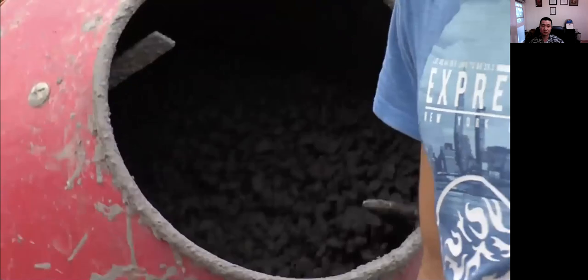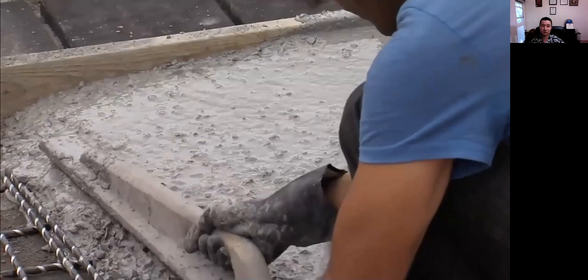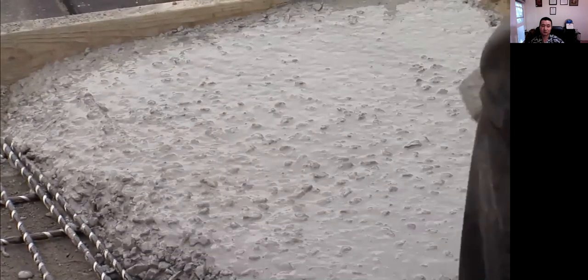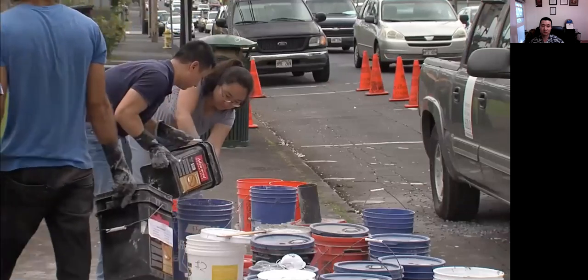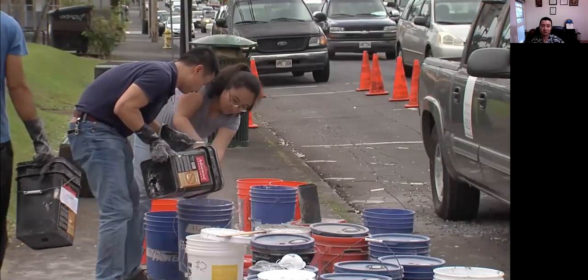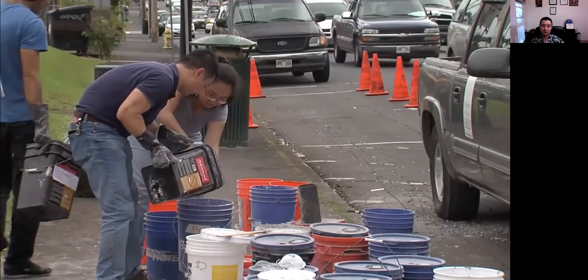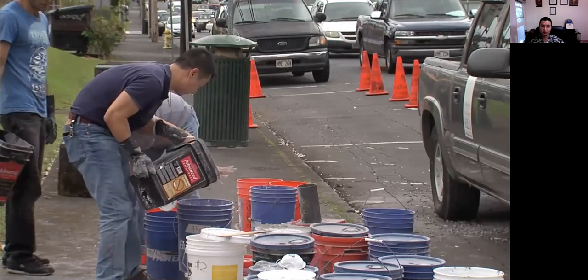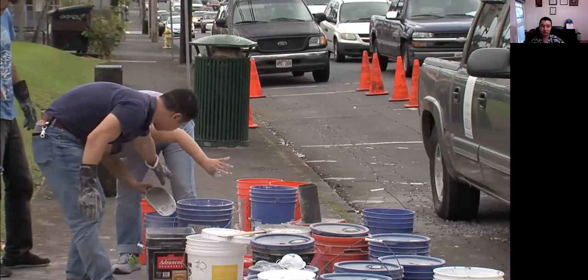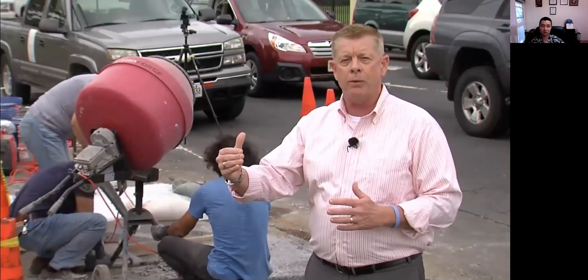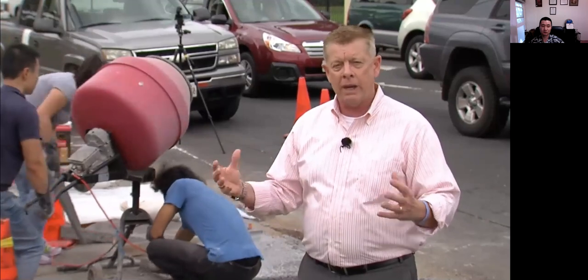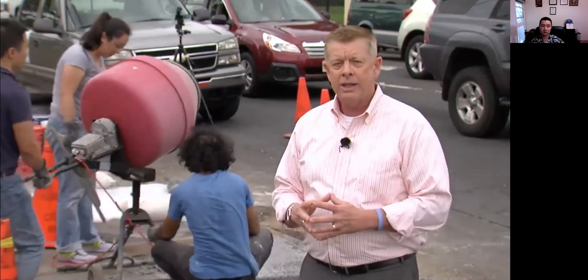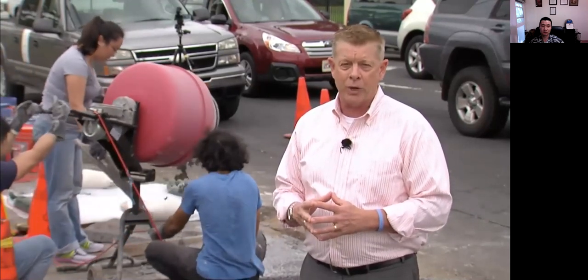So over the next year, we're going to be evaluating different options for assessing the pads here on the sidewalk. Compressibility test, tensile strength. We're going to be taking cores out that University of Hawaii Manoa will evaluate, and then see how these pads perform over the course of a year. So perhaps a year or 2 from now, we could move into other civil engineering projects within Hilo, Big Island, across the Isles out of basalt instead of concrete.